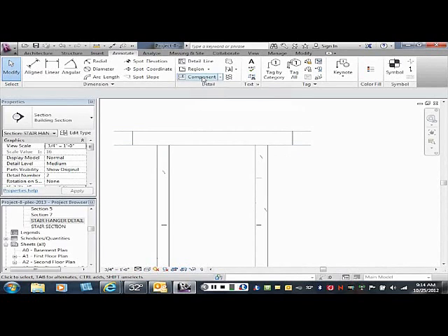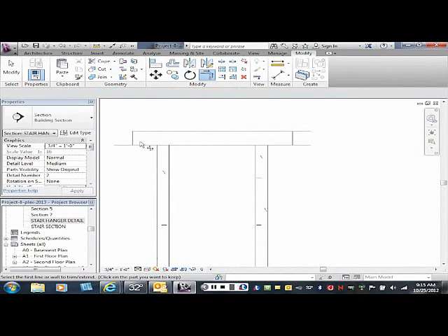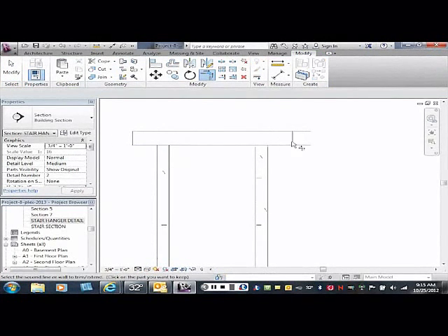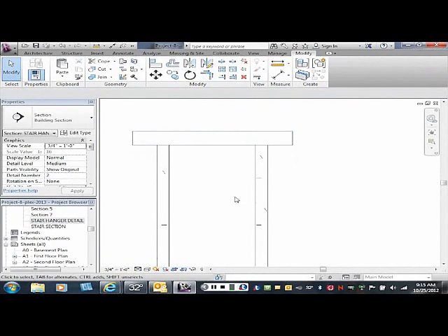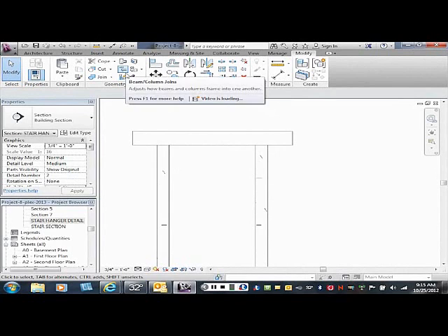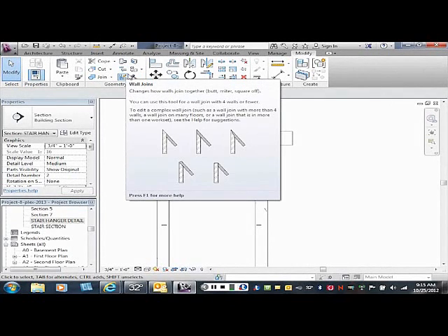So I'm going to click on this and fill out these corners. Okay, now I have 1 inch on each side. Now I can put some trim under there. Some options for trim could be a 1/4 round. It could be actually window casing. It could be some other decorative casing. So you could look this up in a millwork catalog and find out what type of casing you want to put on there or trim.